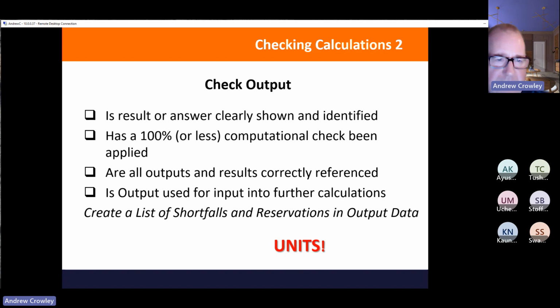And don't forget the units. Many calculations go wrong with the units. That's one of the joys of MathCAD, actually, that it does handle units very well. And don't forget, most of the formulae in codes of practice and national standards are unit dependent, but they don't tell you that. And if you put those formulae in MathCAD, MathCAD will tell you that they are unit dependent.